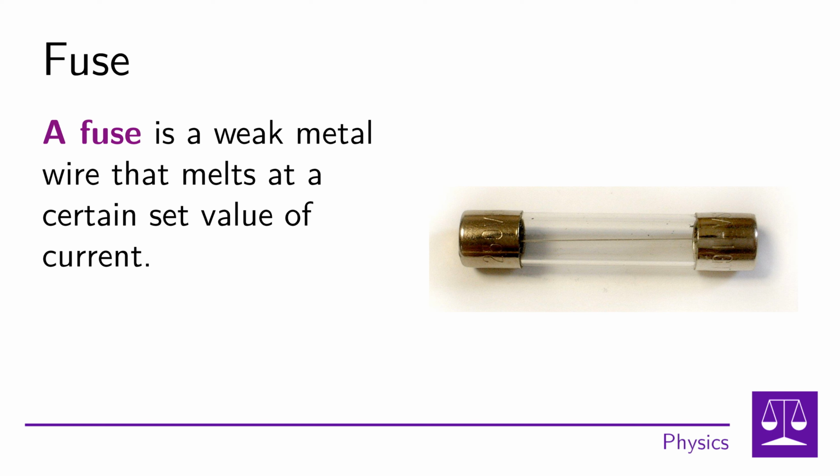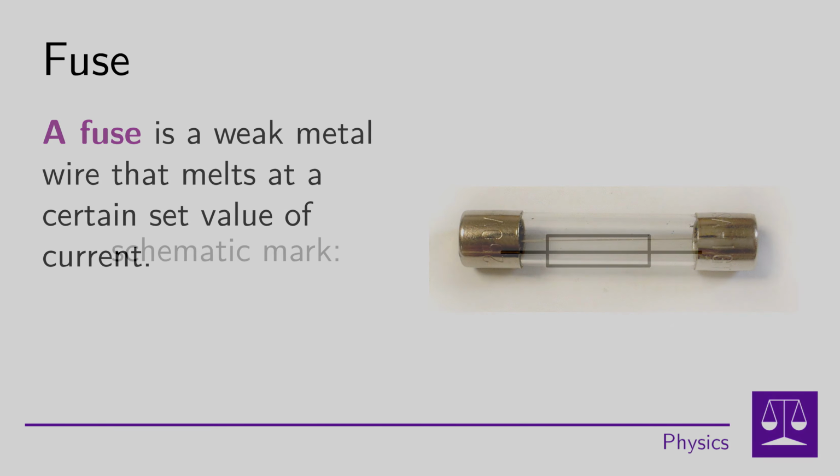The most common type of fuse is the tubular fuse, which is made of a thin glass tube in which the fusing wire is placed. The fusible wire is made of a material that will melt at a certain large current rating. For example, if the rated current of a fuse is 10 amps and we let 8 amps into the circuit, then nothing will happen. However, if we allow an electric current of 12 amps into the circuit, the wire will burn out and the flow of electric current will stop in the circuit.